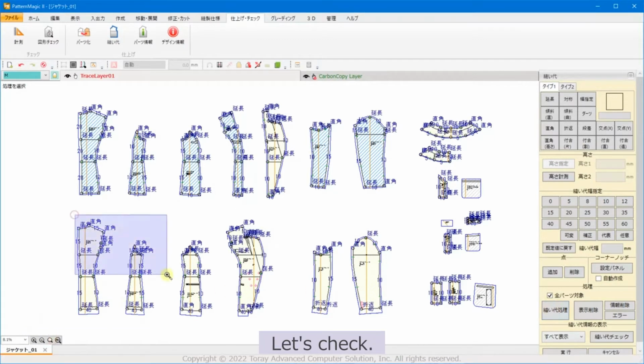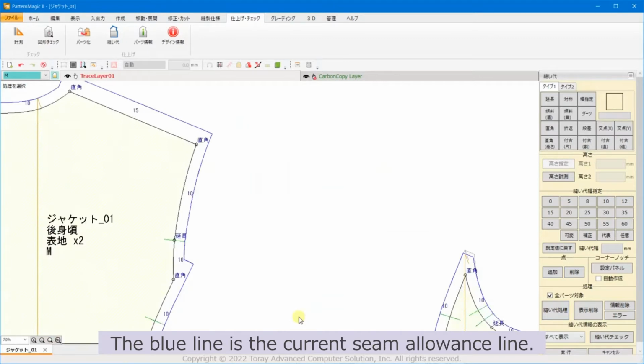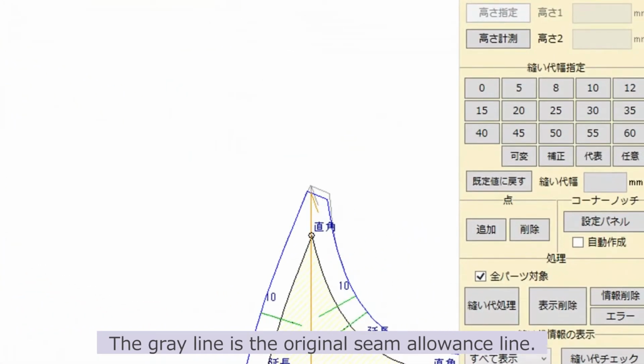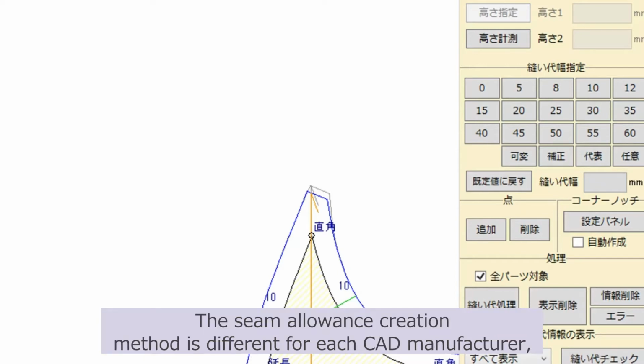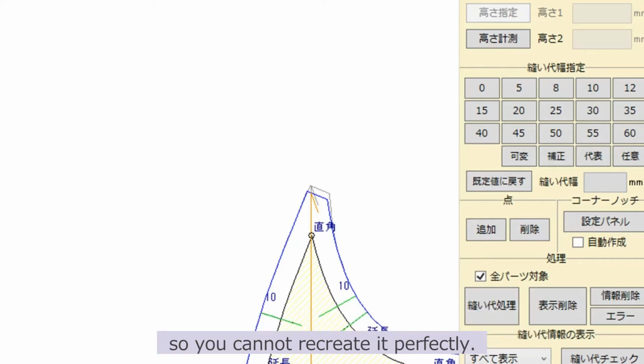Let's check. The blue line is the current seam allowance line. The gray line is the original seam allowance line. As you can see, there are some gaps. The seam allowance creation method is different for each CAD manufacturer, so you cannot recreate it perfectly.